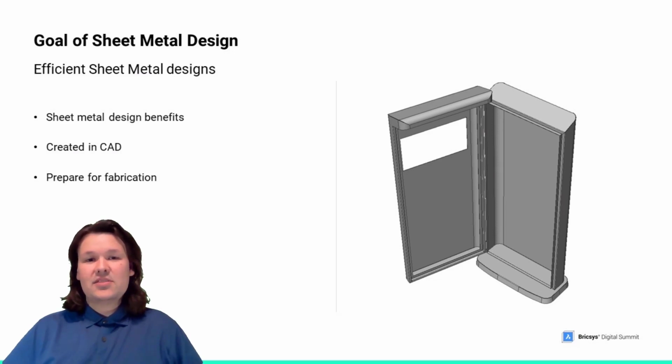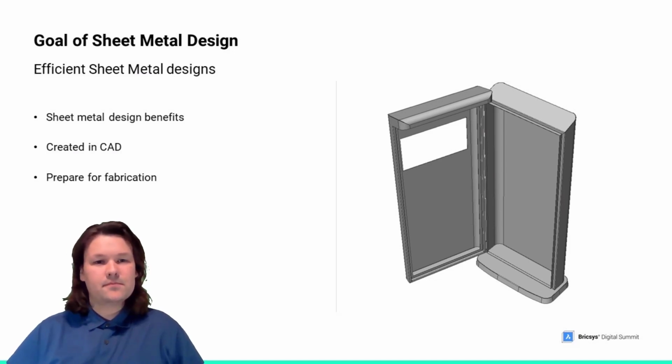These points are especially true if we compare them to that of a part that is cast, where you would need an expensive mold to begin with to create a part, and then the finished part is still susceptible to the problems I mentioned earlier. So in addition to these benefits, this also allows the sheet metal parts to be easily replaceable, sustainable, and cost-effective as well.